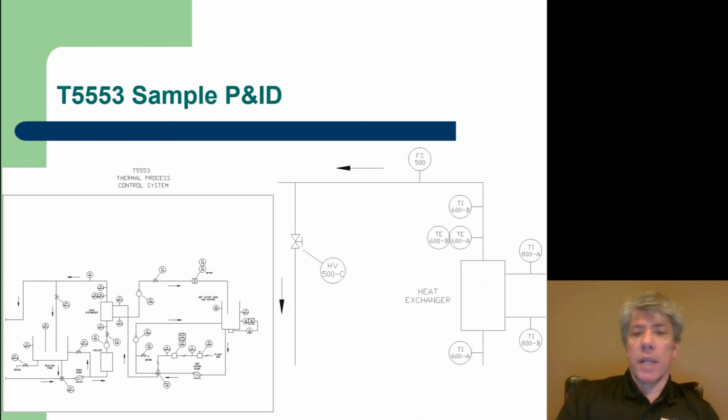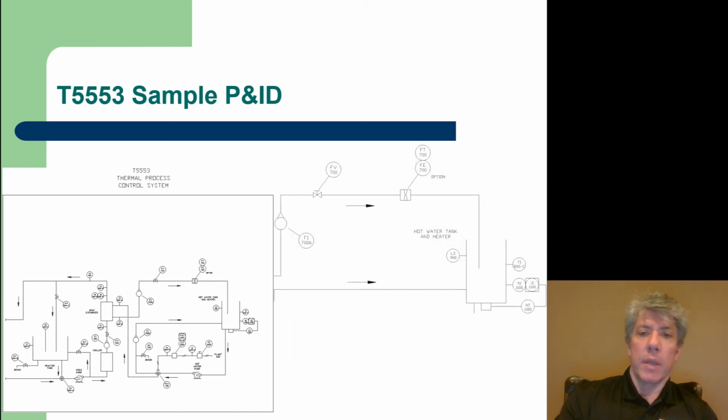If we look at the upper left side, zooming in on it, we can see a heat exchanger. Again, not a standard symbol for that heat exchanger, but there it is. And FS is most likely a flow switch, FS500, and all of these we've seen before. TE would be temperature element. Again, I don't know why they don't include something about transmitting it or indicating it.